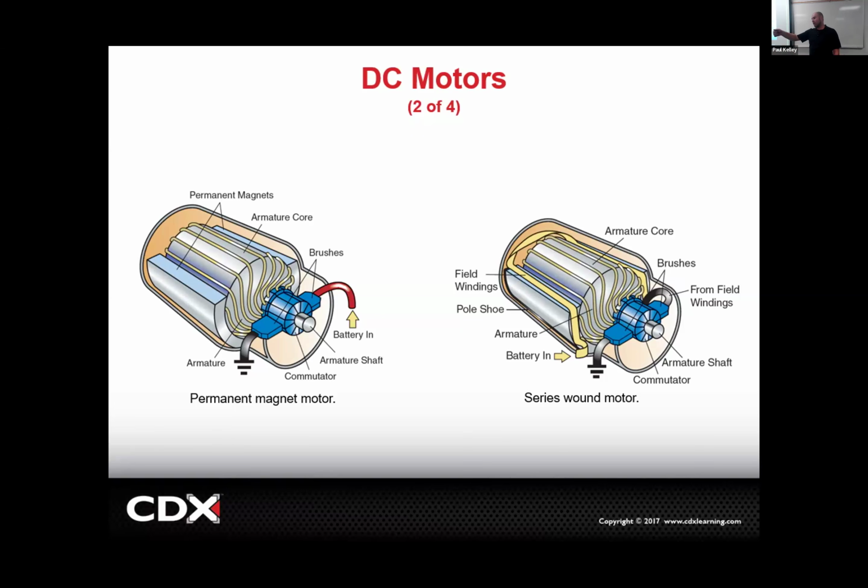It's helpful if you can have somebody crank it while you punch it, because at that point we could be sending 12 volts here and ground here, but if the brush is a little stuck and you hit it and it jars it just a little bit, all of a sudden it makes the connection while you're still trying to crank it, giving it 12 volts and ground, and it can actually get it moving. Then I can drive the vehicle in, and that way I don't actually have to push the vehicle in. So that'd be mainly the reason, right?